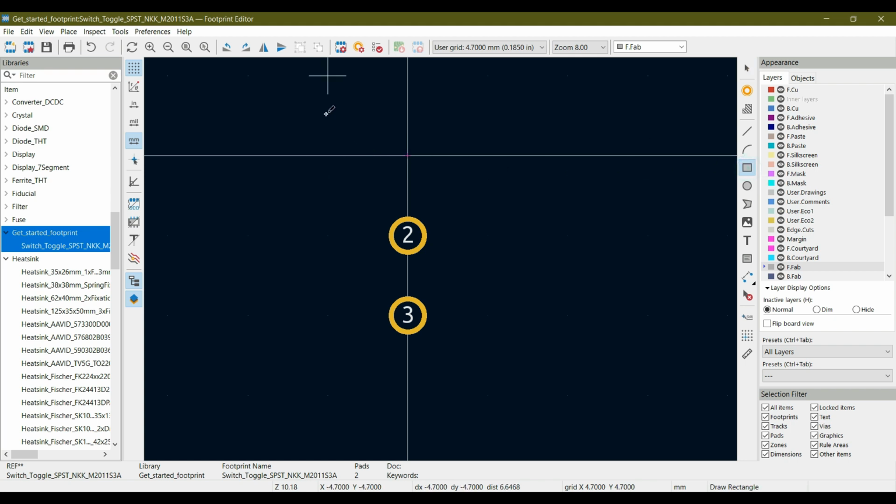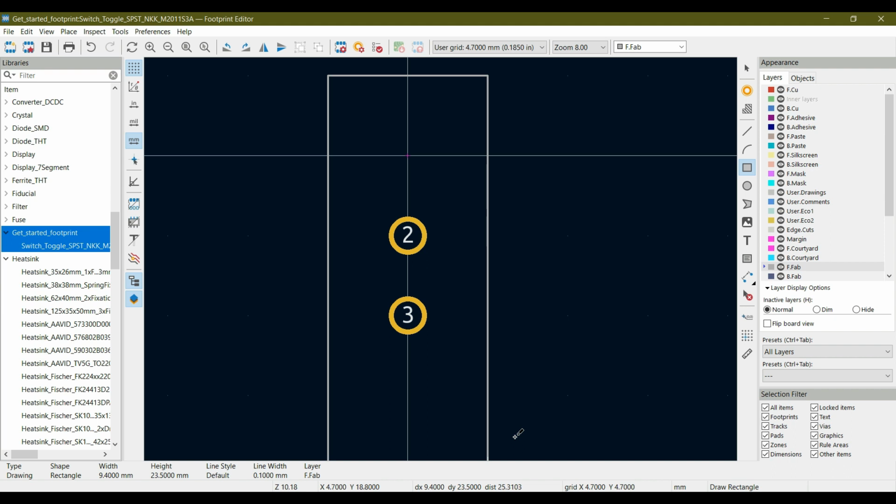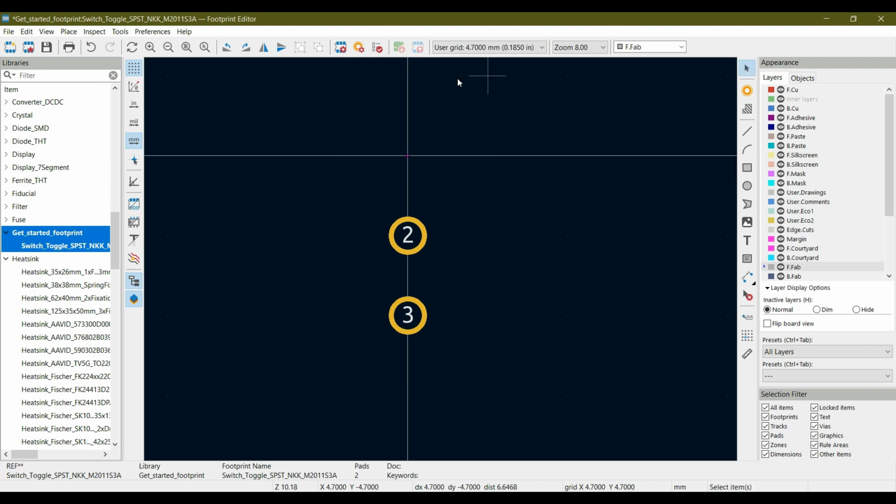This is just a rough boundary that has a length of 13 mm and a width of 7.9 mm. So let me delete this, and let's be very precise while drawing the outlines, because these are the dimensions that are fed to the machine while fabricating the PCB.